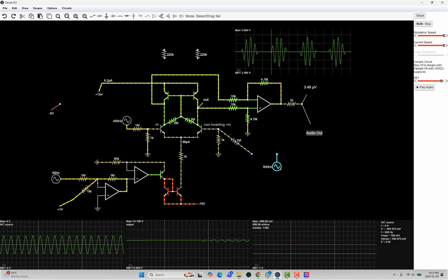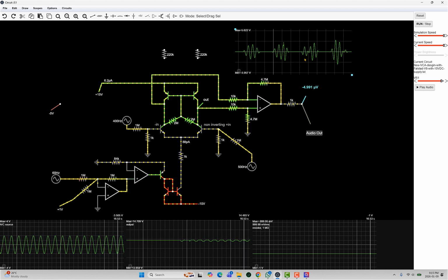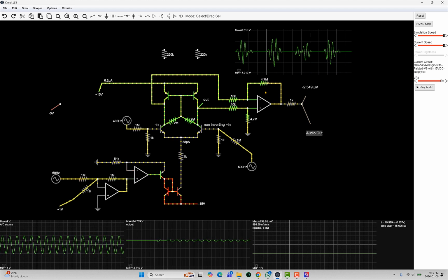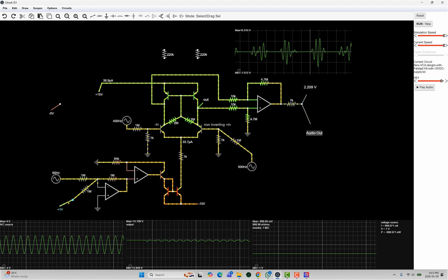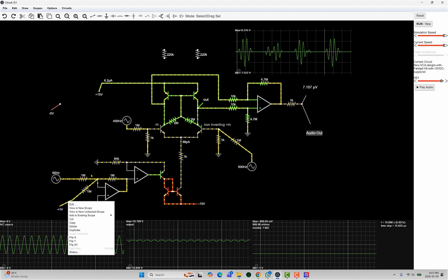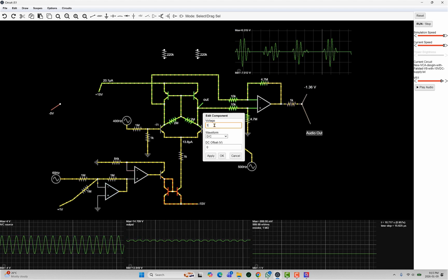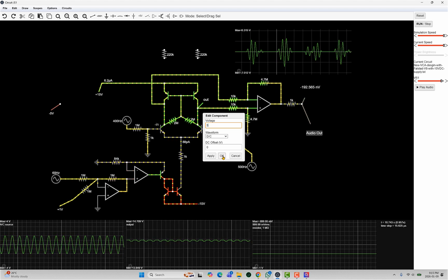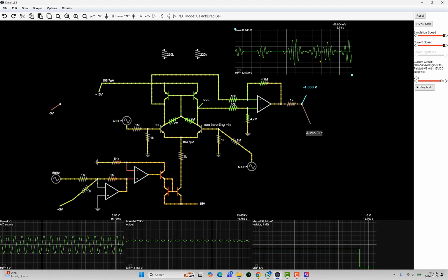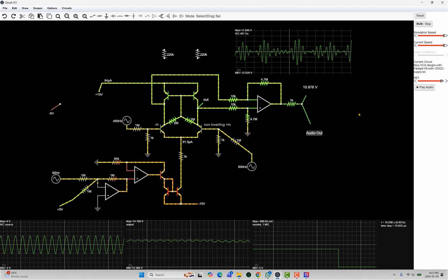Not only that, you could actually mix two frequencies in, just like I did before when I created the train sound. Now you can see the wave shape for this sound. I kind of think it sounds like a train. The reason it's kind of missing the gaps is you need that DC offset, and you can work out all the math on that if you want, but it needs a certain amount of DC so it doesn't hit the zero line like that. So I'll just edit this. What I found is you need around 5, and then you can mix the AC here, and the DC is mixing into this terminal, and you see it's a lot nicer now, right? And so you can play around with these values and get all kinds of different effects.